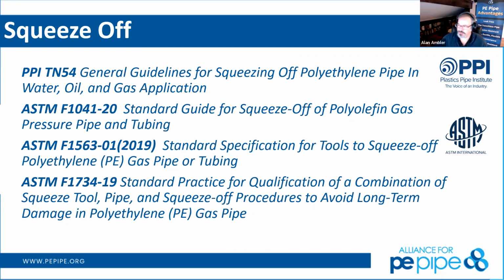We've had a good question about pressure testing. The question here came: is there any way to verify the integrity of the pipe if the hydro test pressure exceeds the pressure surge, or is it just deemed a failure and pipe cannot be used? So I wanted to just take a step back on high density polyethylene itself. Surge pressures with high density polyethylene, the pipe itself is actually rated to 1.5 times the operating pressure of the pipe for recurring surge. So that's about 50 cycles a day that can happen. And then 2 times that operating pressure for the occasional surge.